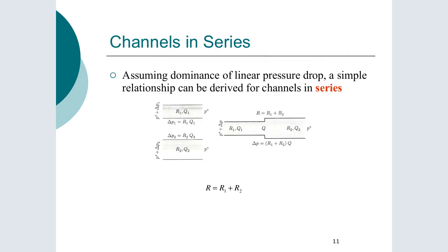Now, if we have channels in series and they may be different size, so this is a typical thing we do, we'd have connections and fittings between them. We know that in reality, there's going to be a reorganization of the flow in this region here where they're joined together. So the streamlines expand out, and therefore we have an acceleration taking place. So this is an inertial region that I've highlighted there. Now, if that region is small, the contribution of that region to the overall pressure drop will be small. And that's very often the case with microfluidic systems, especially where we have quite long channels.